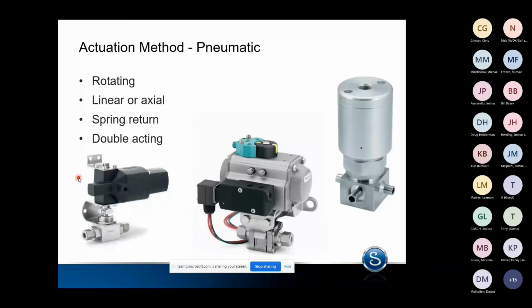I believe they end up being special ordered. They're not all stated in the catalog. There's some that are NEMA 4, 4X, 7, and 9. And then there's some that are Class 1, Div 1, but they're not all explained as a standard in the literature. So if you do have an opportunity that needs to have explosion proof or something else standard wise with solenoids, please let us know and we can make sure that we get you the right one.